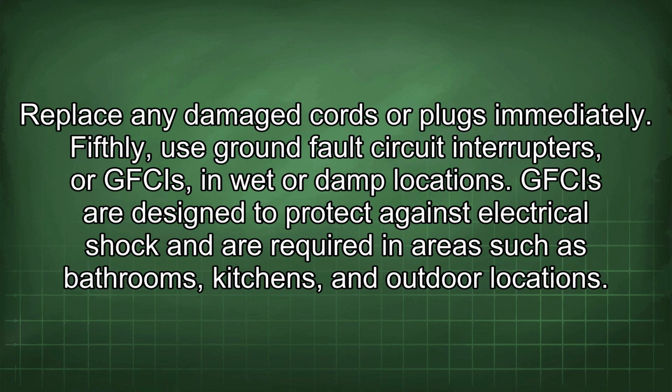Fifthly, use ground fault circuit interrupters, or GFCIs, in wet or damp locations. GFCIs are designed to protect against electrical shock and are required in areas such as bathrooms, kitchens, and outdoor locations.